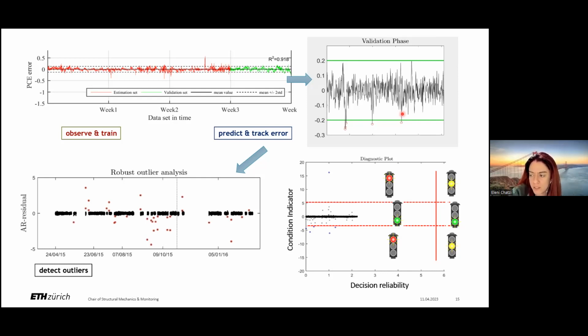instances within which the system is not behaving as expected, but in fact, we also have a range of influencing agents, such as, again, the temperature, in this case, or the orientation of the wind, which is outside of the regular bounds. In these cases, we're issuing an orange alarm, which notifies the operators and the owners of these wind energy sites that something is off, but it could possibly be because we have a new and previously unobserved situation of the dynamics.